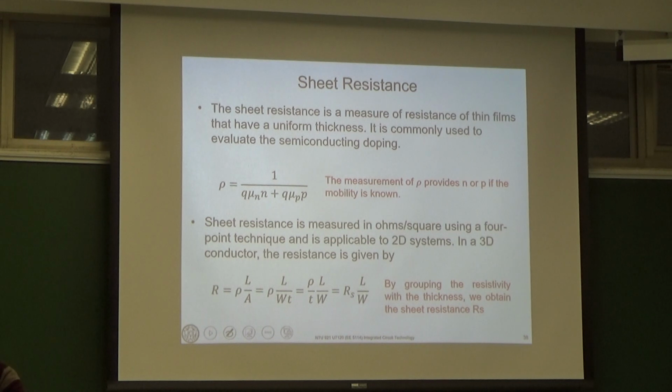Okay, and then we can determine not only the type, N-type or P-type substrate. It's also very important for us to know the sheet resistance. So how can we measure the resistivity of the wafers? This is the bulk resistivity that we often see in some textbooks. It depends on the mobility, and on the electron and hole concentration.